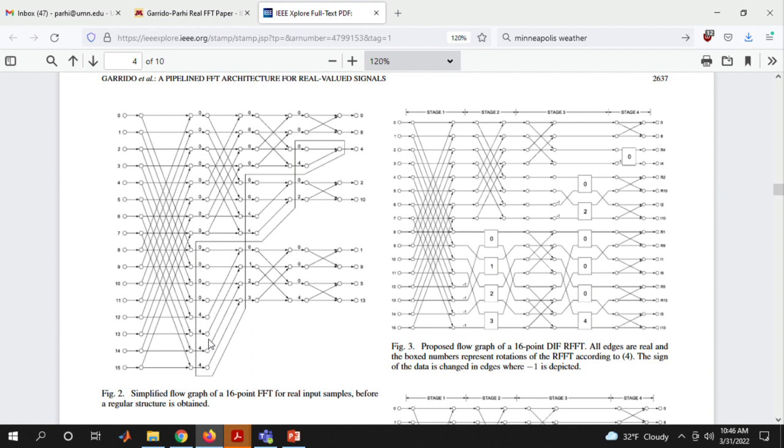Okay, there is a little more going on. There is some twiddle shifting that I haven't talked about, but ultimately, these things used to be w to power 0, 1, 2, 3, 4, 5, 6, 7. Some twiddles are pushed to the right. Then w to power 0 is all 1, w to power 4 is minus j. That means you swap real and imaginary. There is no real multiplication going on, and once you swap them, expand these half complex butterflies, they become real butterflies. So I fill that up, and at the end, after you fill all these up in the real butterflies,